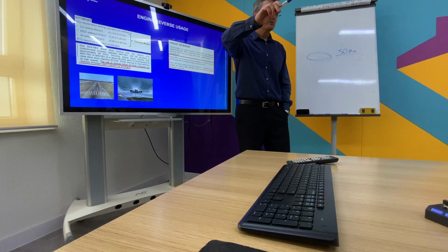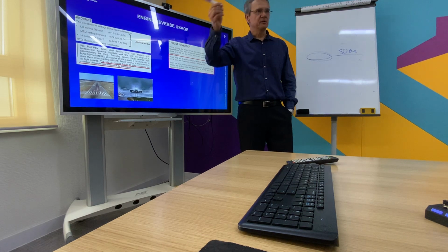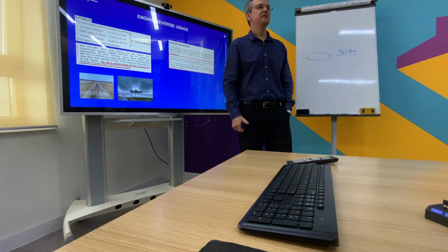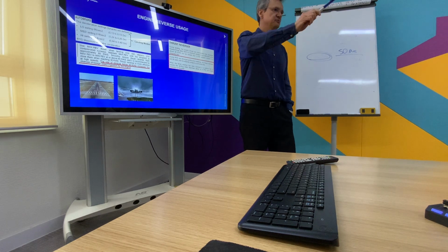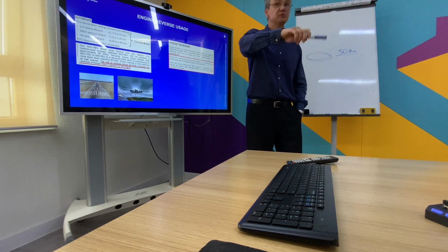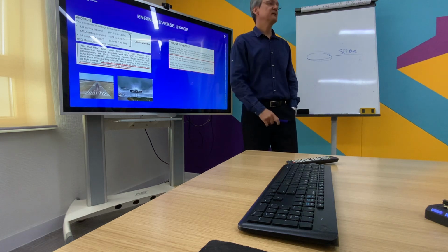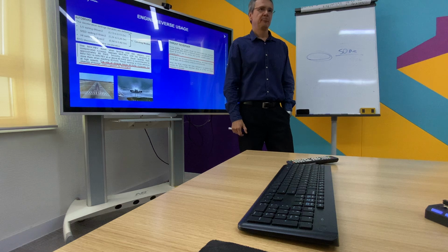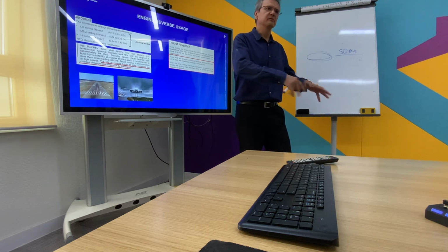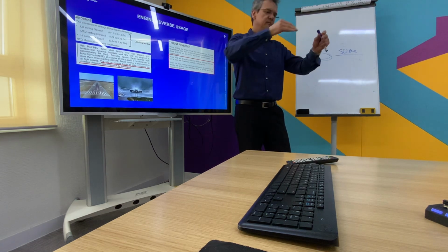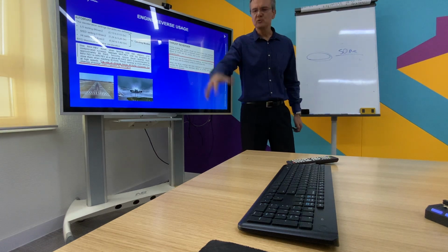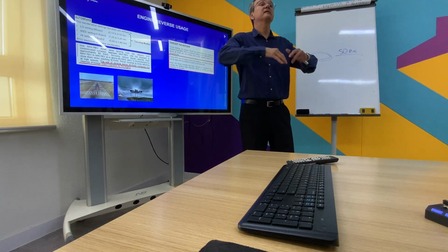The temperature on maximum reverse on the ITT, on the E2, goes up to 790 degrees. It comes from around 560, 600 to a peak of 780 to 790 degrees. And I see many pilots, not here, worldwide, landing on a dry runway, long runway, and using maximum reverse unnecessarily.